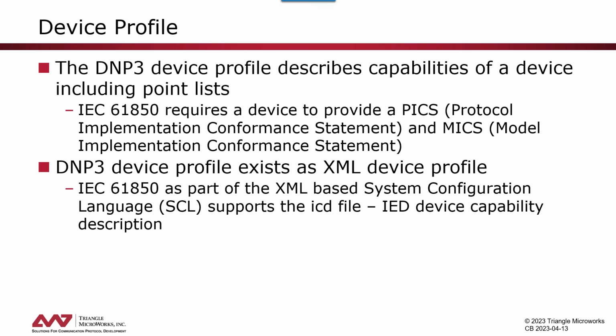MICS, model implementation conformance statement. So PICS corresponds to the capabilities, the MICS to the point list, which is in this case the 61850 data model. DNP3 device profile exists as an XML device profile. In principle, they are required to be provided in XML.